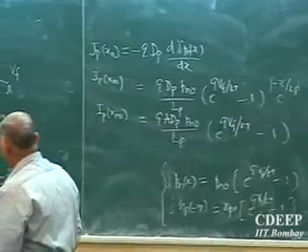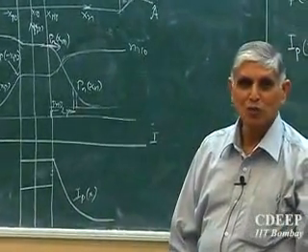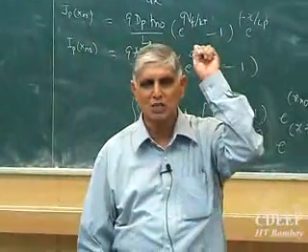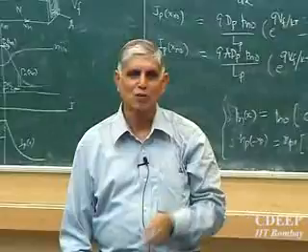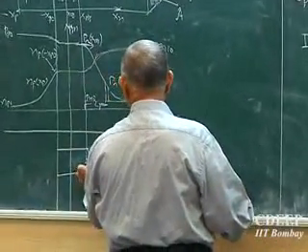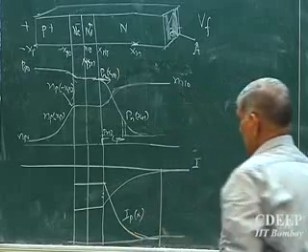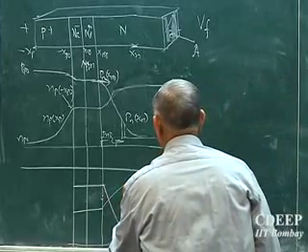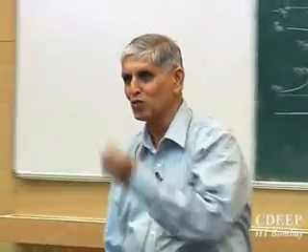Okay. Now, the net current is I. So there must be an equivalent current from electrons making up this current, because I keep saying at every space point the electron current plus hole current must be equal to the total current. If the total current is constant and this is the hole current, the remainder current must appear from electrons. So the electron current may look something like this, at the same point. It should be complementary to that. As it decays, in the same way it should increase, and this is my I_n(x). Now, we have not talked about where this current is coming from.